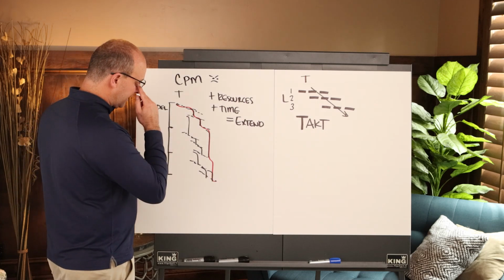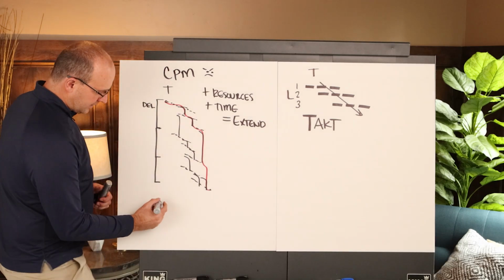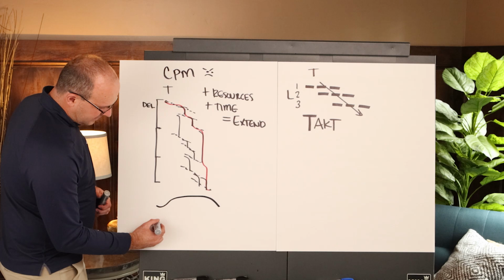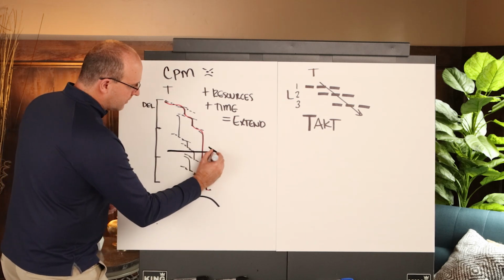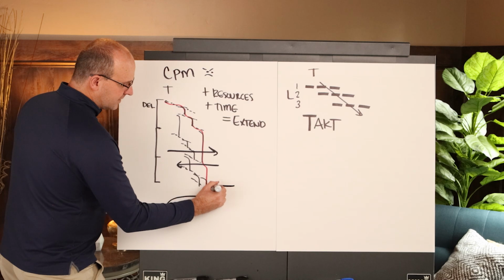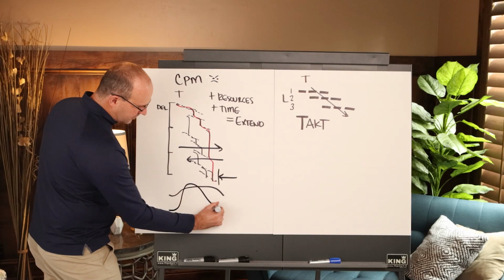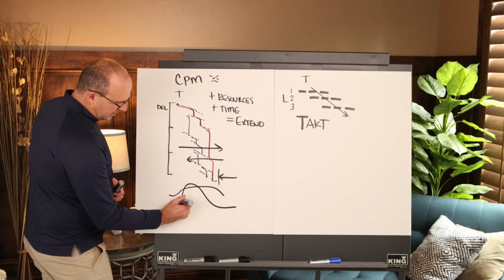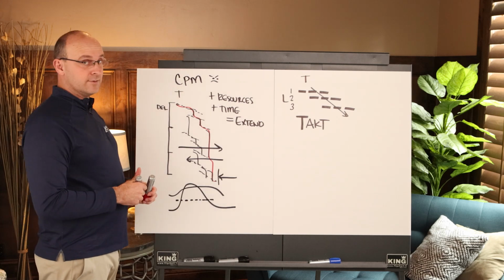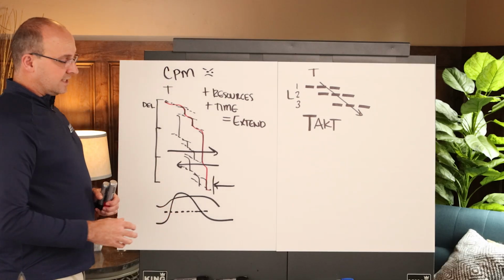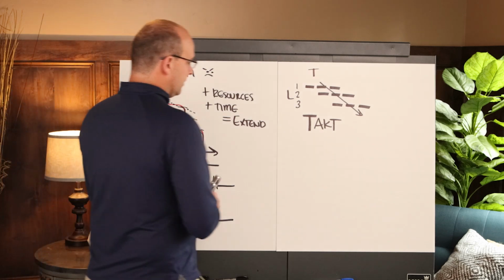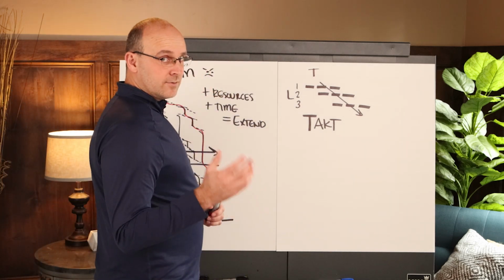But one of the worst things that happens is that instead of creating a nice, beautiful, leveled work and process on a job site, what CPM will do, it does the forward and the backward pass and will move everything to the left as much as possible, so it will increase your work in process above your capacity to actually build work. So it's really problematic. So that in and of itself will mean that you, and let me go ahead and draw this, will start to delay right out of the gate.